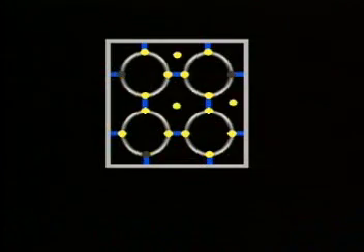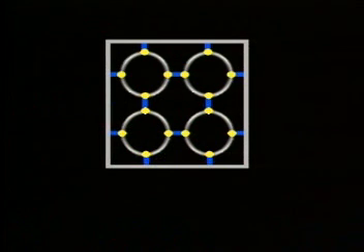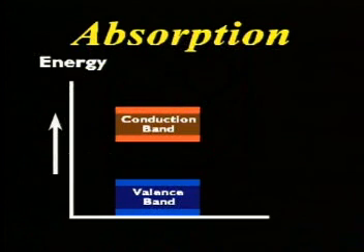Photons can be absorbed by semiconductors, moving electrons from the valence band to the conduction band and creating electron-hole pairs. In order for a photon to be absorbed, its wavelength must match that of an energy level transition the material is capable of. Thus, certain materials can only absorb photons of specific wavelengths. For this reason, source and detector wavelengths must be matched. Photodiodes work like LEDs in reverse.